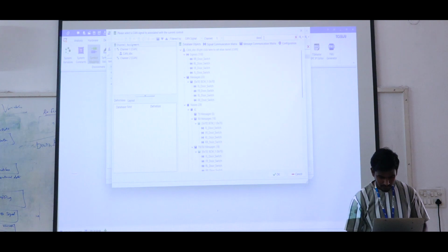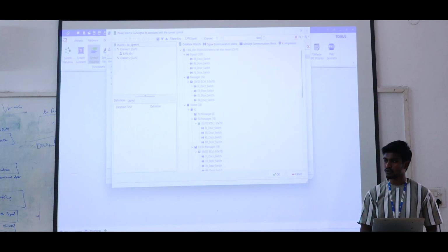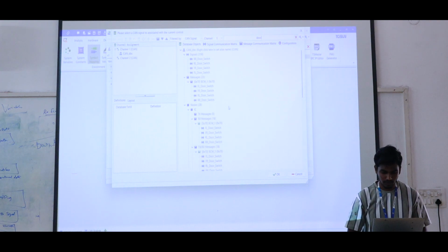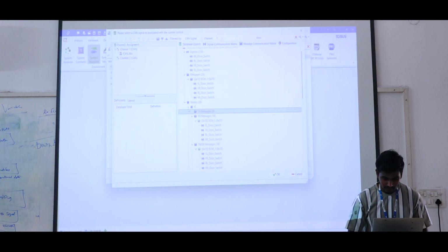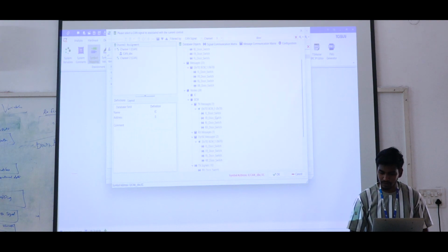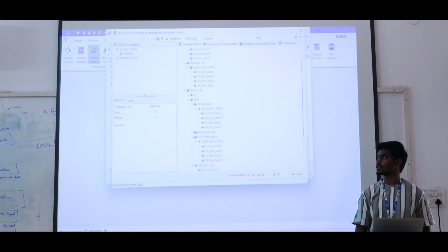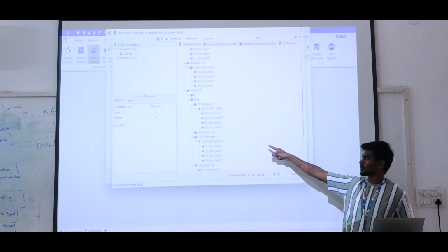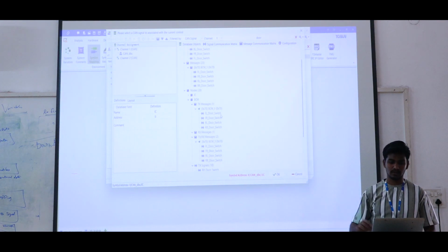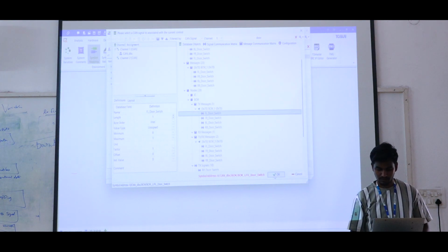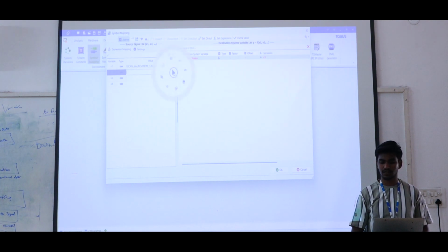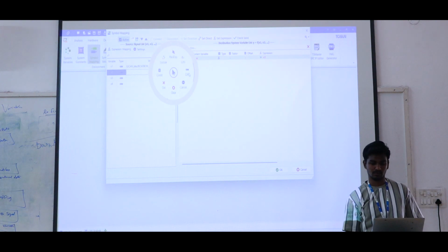You have to select the signal. You just select the door. You can type door. Type door. So it is transmitted by the body control module ECU. Okay. So we are having 4 switch values: FR door, RL door, FR door, RR door. Okay, 4 door switch values are there. Just click and open it. So for X1 as an FR door, X2 as an FR door. Like that, you have to navigate the different door switches.